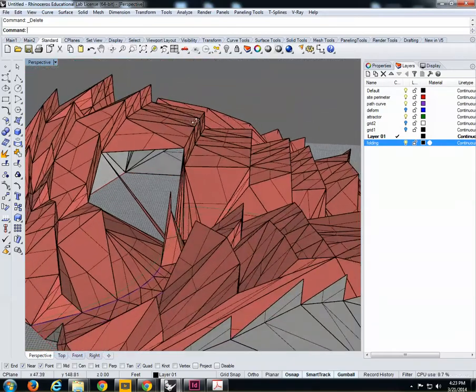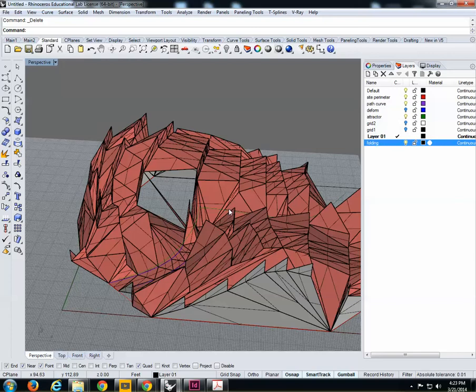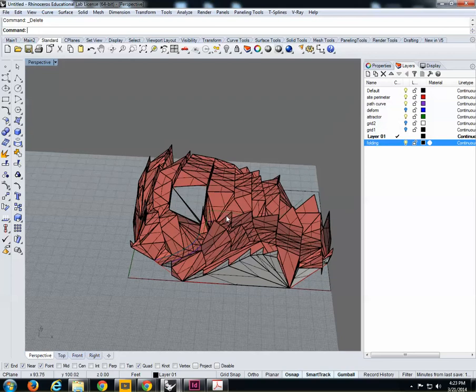Okay, very fast now I'm just introducing one extra command, the pipe command, just in case you want to visualize lines. So for your diagrams over there, if you have a line element that connects specific points of the city, maybe the pipe command is a good command for you to visualize this line with thickness. So let's do that all together now. So for those that didn't manage to go to this step of the piping, try to follow me. We still have 10 minutes to go slow and do it all together.